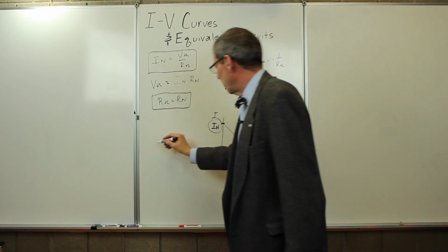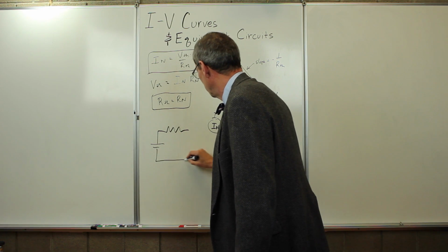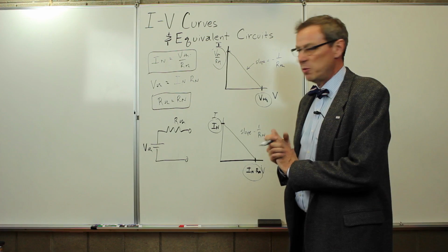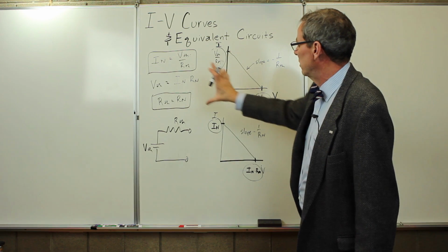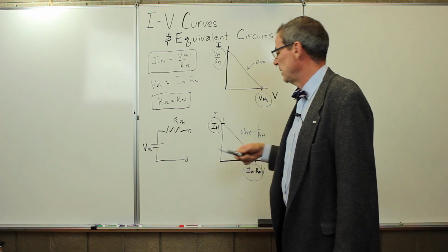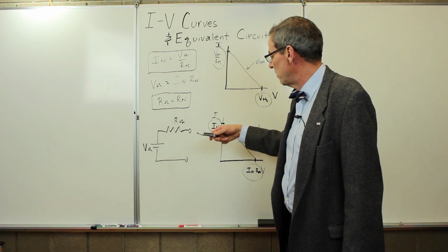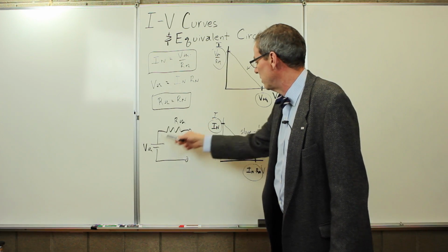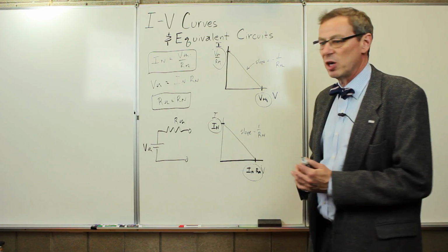The one that's going to be particularly useful for us in this course is the Thevenin equivalent, because that one is something we will equate a lot of things to. So that's the one we will look at a lot as we go through this course. But here we have Thevenin equivalent, Norton equivalent, same IV curves under some basic assumptions about this, which means that they're equivalent. And what we'll show is that a lot of the circuits that we have in this course can either exactly map onto these or can approximately map onto these in certain regions very, very well. So we can characterize them by this very simple circuit, which is just a voltage source and a resistor. And we don't have to worry about more complicated things inside.